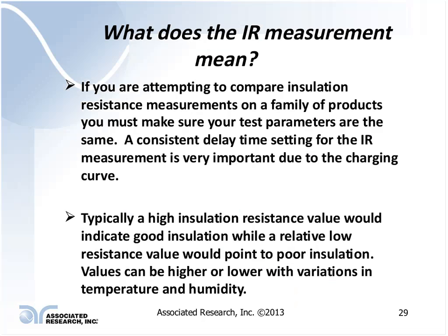If you're attempting to compare insulation resistance measurements on a family of products, there are several parameters you must take into account. You must make sure that you're using a consistent delay time in taking your reading. Again, this is important because of this charging curve that we talked about. I recommend making sure that you're using the same type of test equipment.